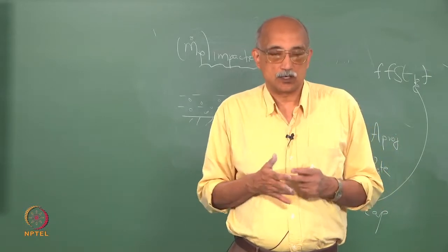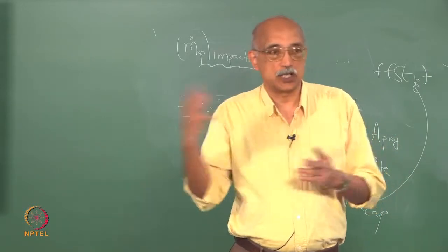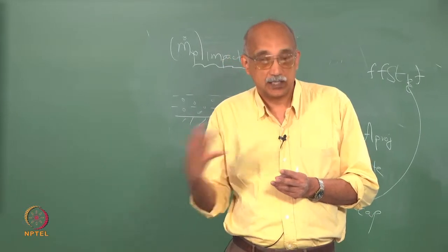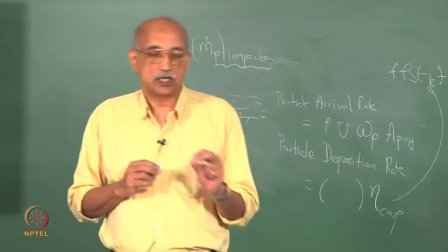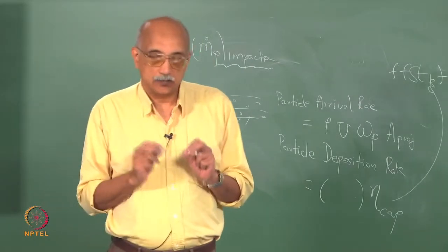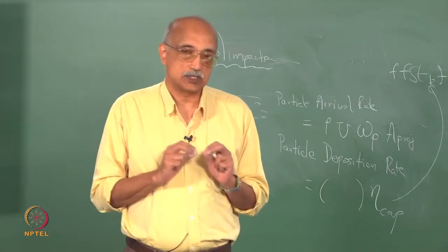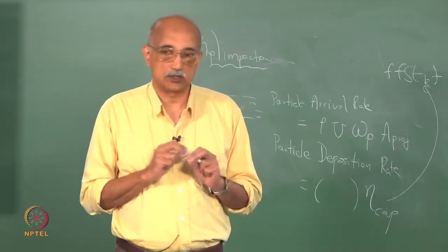So, if you get results on a small system, you have to be able to scale the results to a larger system. Scale up, which is something that chemical engineers are supposed to be very good at, only becomes possible if you can identify and derive the most relevant dimensionless numbers for every system that you are dealing with.